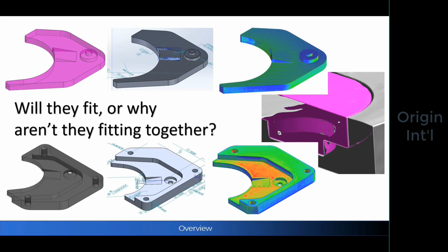Yeah, it's one of the things that we've fixed for one of our clients where both parts were dimensionally accurate and to the drawing, but they wouldn't go together. This is just an example of that workflow. It's not on these two parts. The two parts had never been in the same building, and they realized they were missing callouts, and one of the tolerances on a couple of the features was wrong. It was a red flag a lot earlier in the process, is what it really led to at the end of the day.